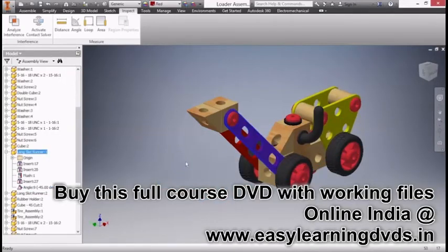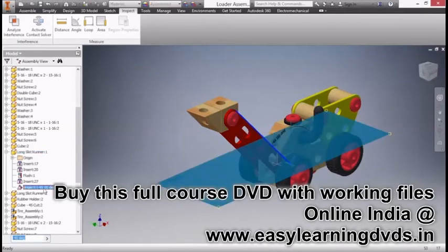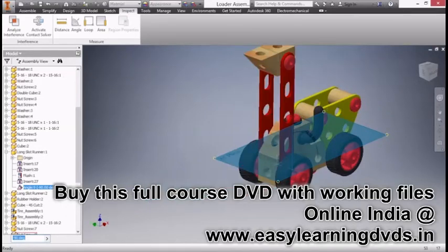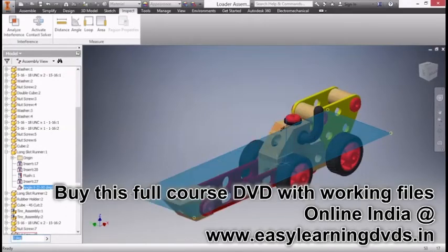It's being held there. If I change this angle value from negative 45 to 0 by simply changing it in the bottom there when it's selected and hitting enter, it's going to update that geometric relationship to have that drop the bucket down. Now I can also have that be negative 90, and that's going to go straight up, or return it back to the 0 value.